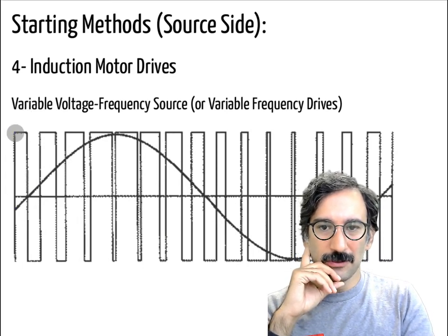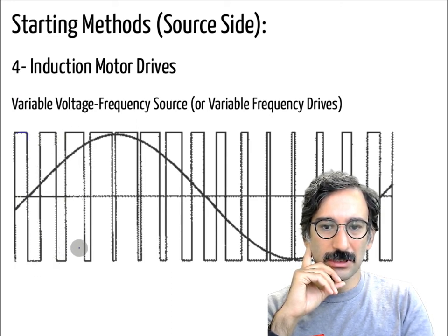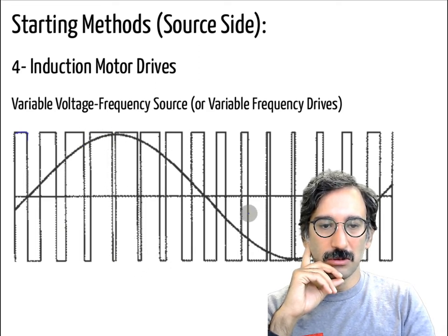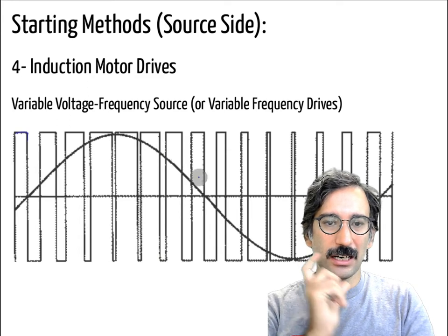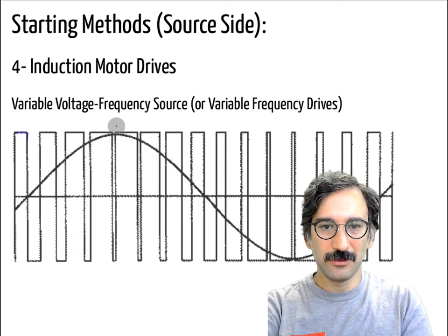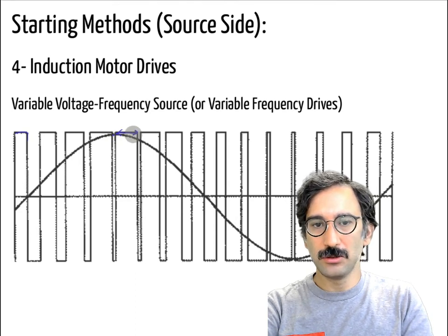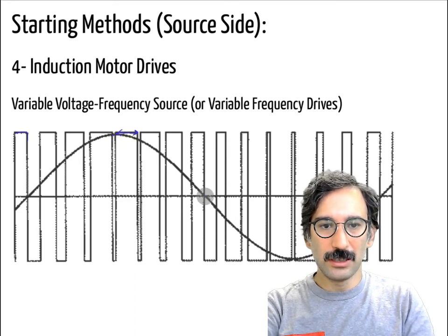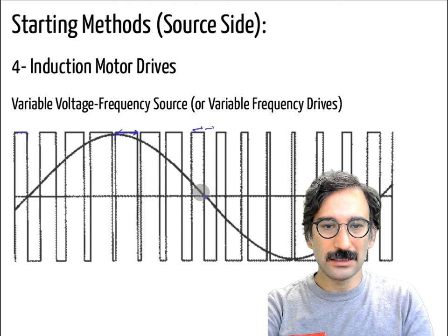Technically, if you connect your oscilloscope and look at really high frequency, it can be tens of kilohertz, so you will have that kind of varying PWM width. Whenever your sine is at maximum, you have the maximum duty cycle, and whenever it is around zero, it is 50% positive, 50% negative, so they cancel each other.